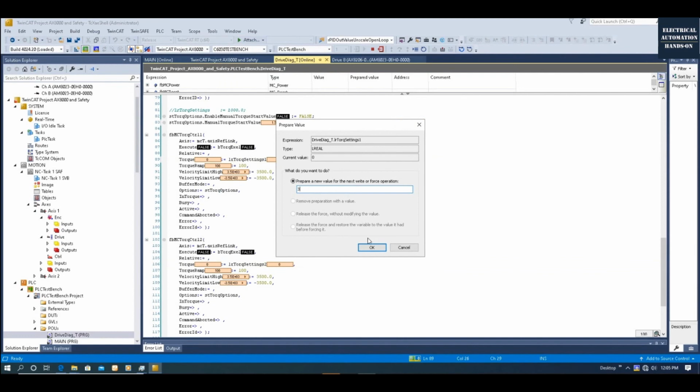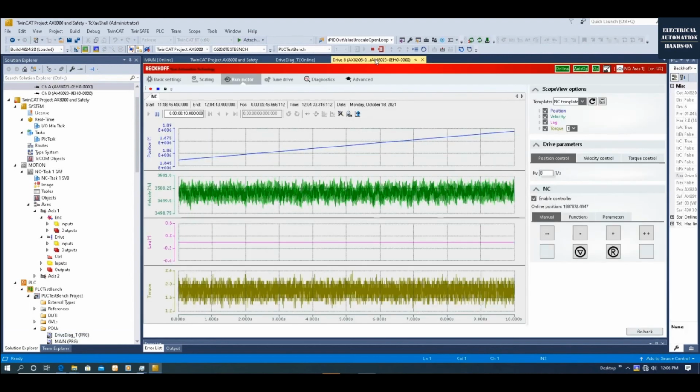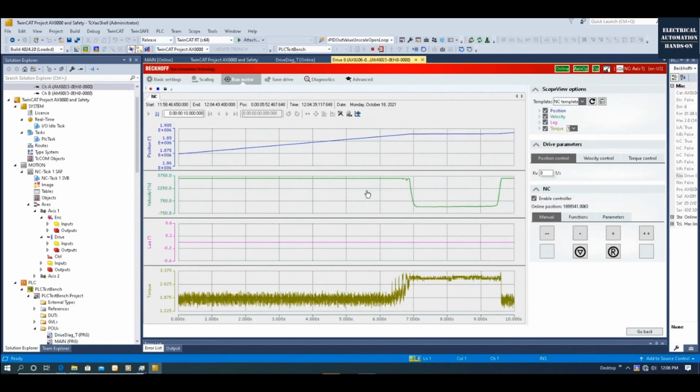All right, now for torque control 1, we can set 3. And for the second torque control, we can set 5. Okay, we are using two instant function blocks here. We can trigger the first one. For the first instant function block, we set the torque set point, that is 3%. So we apply the load and we can see the highest torque is held at 3%.